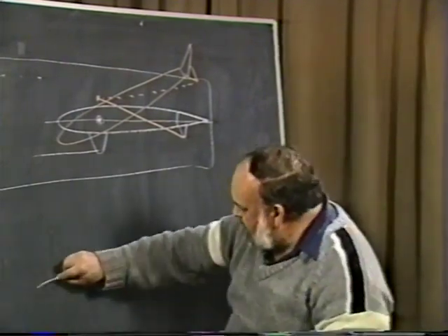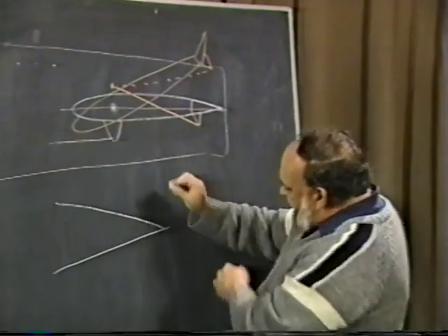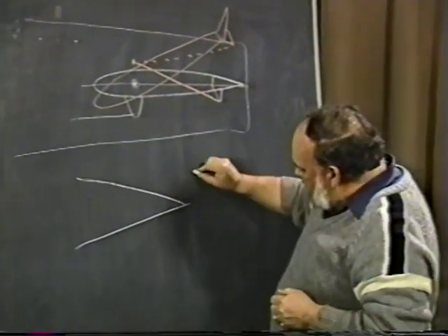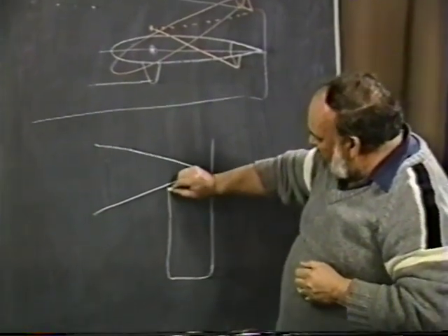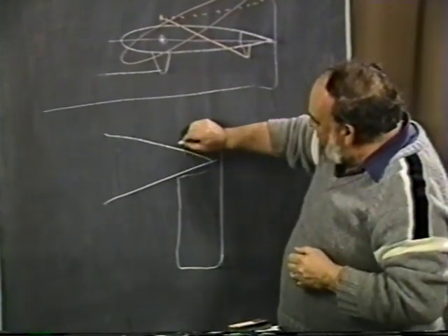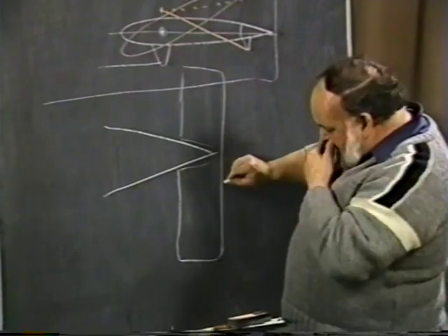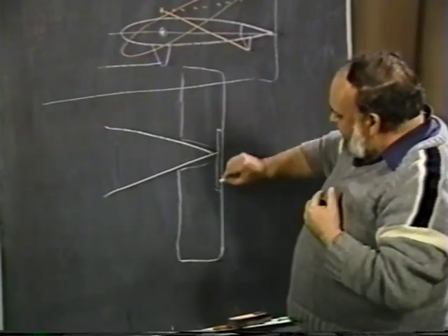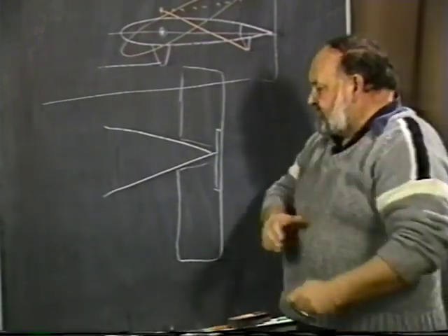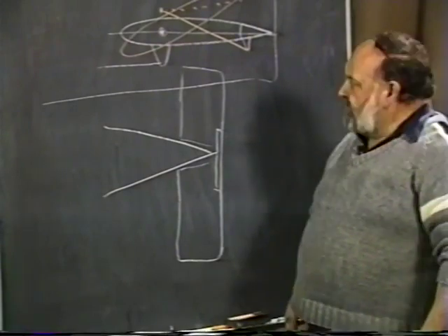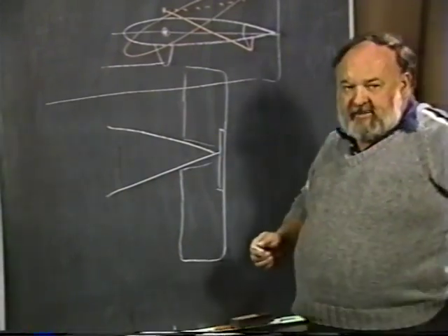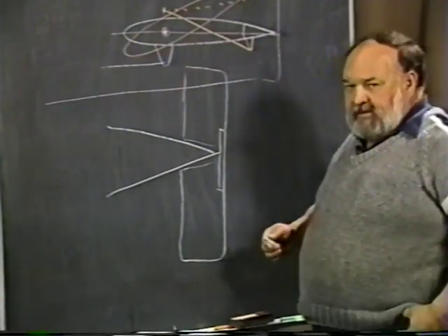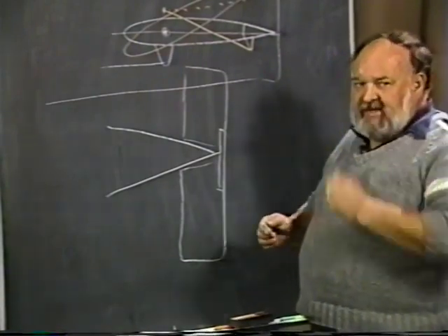From a top view, let's assume this is the fuselage. And, well, let's take even the case of the Bede 4 where we had essentially a rectangular planform for the horizontal tail back there. We put the servo tab in this region in here. Now, everything's perfectly fine. Everything's balanced real nice. It pivots on the quarter chord, the servo tab, anti-servo tab that is, goes there and gives you the stick forces you want and everything else. But there's a couple things you have to be concerned about.